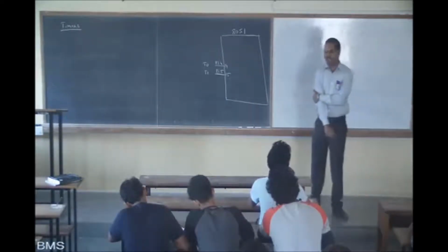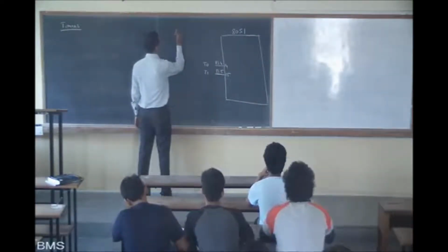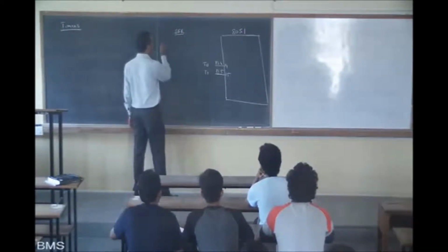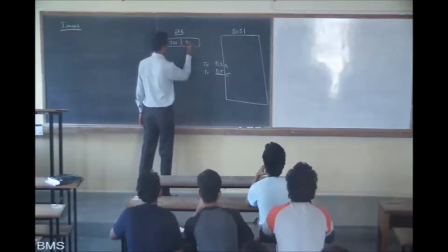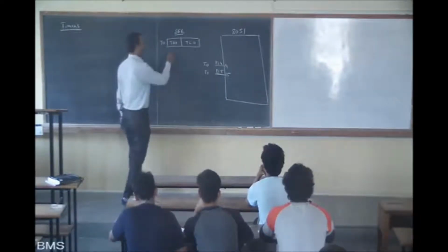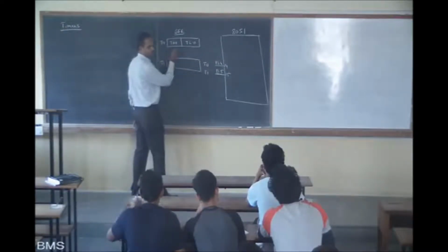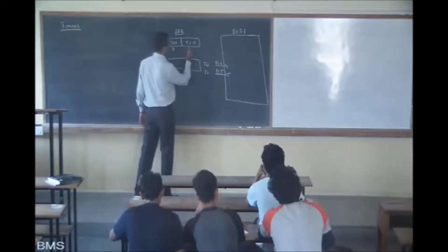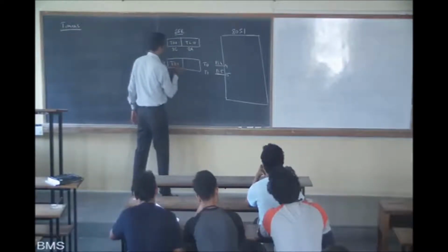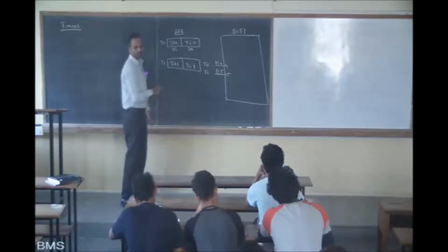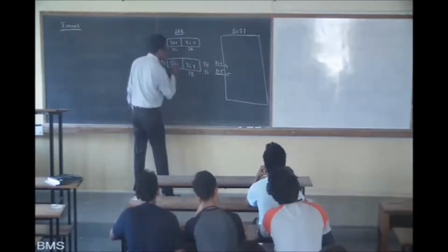Right. These two pins, which represent a timer, also have a connection in SFR. In SFR, you have T0 represented as TH0, TL0. Check it and tell me what the address is for these two. T1 is represented as which one? 8A, and 8C. Similarly, TH1, TL1: 8B, and 8D.